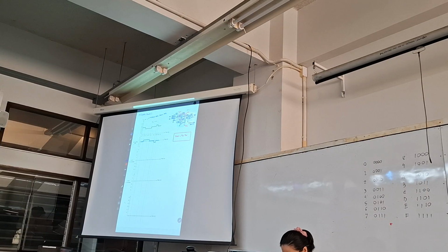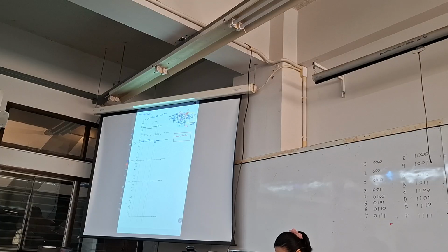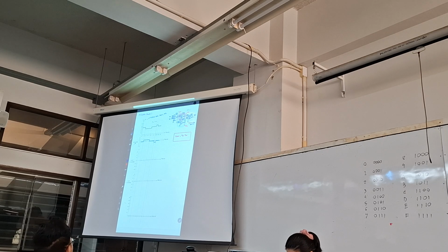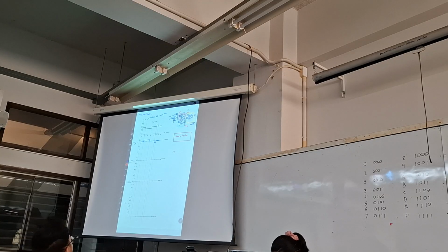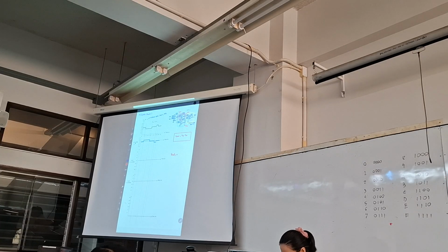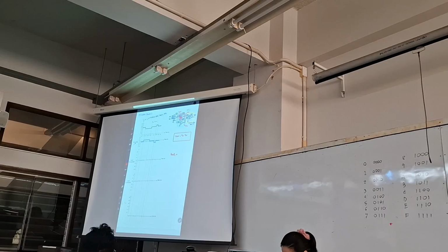The next step we have to evaluate V out from the P controller here. First, we have to understand the output equations of this circuit. As we know, it is an inverting amplifier, so we simply write down the output equation. V out 1 should be equal to gain multiplied with input. Input of this circuit is V, and gain is RF divided by RIN.